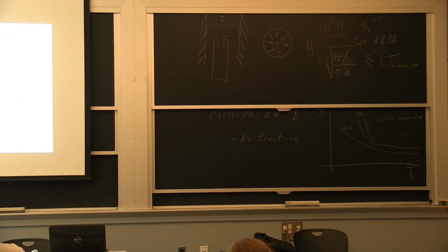So the aluminum, again, has more deformation slip systems and has partial dislocation, so it's not as sensitive to temperature. The energy to have one step moving is less. Therefore, the thermal activation is less, and you have less an effect of temperature.